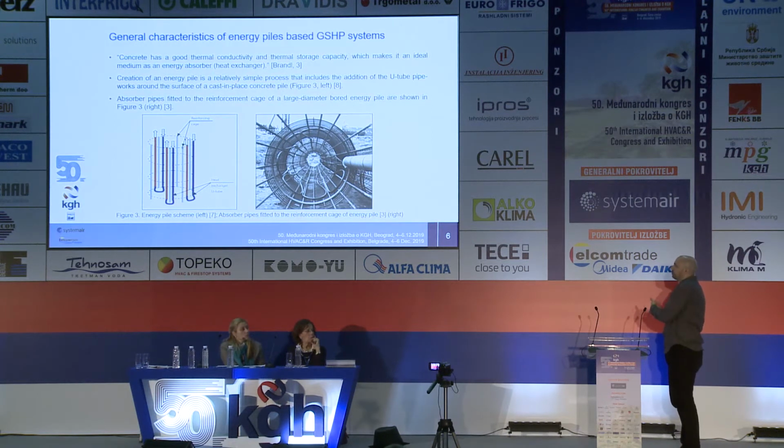I think most of you know this, but concrete has a good thermal conductivity and thermal storage capacity. Because of that, it is an ideal medium as an energy absorber. In these two images, we can see the way that absorber pipes are incorporated in a reinforcement cage of an energy pile. So basically, the creation of an energy pile is a relatively simple process, and it includes the addition of the U-tube pipe.